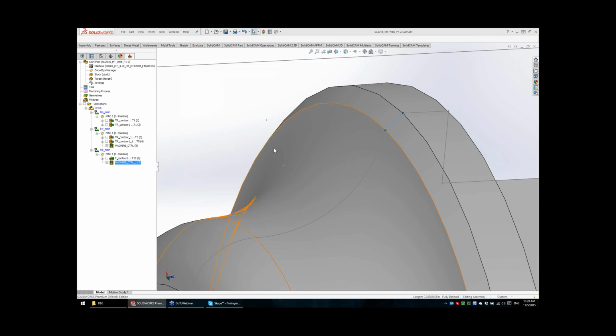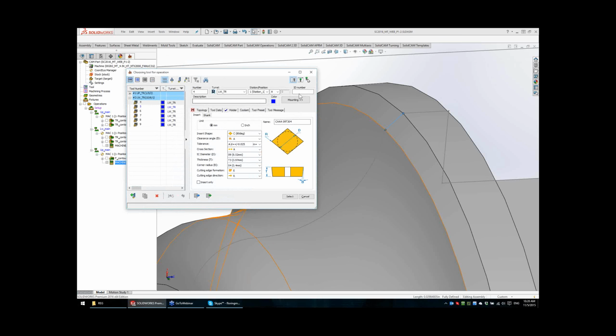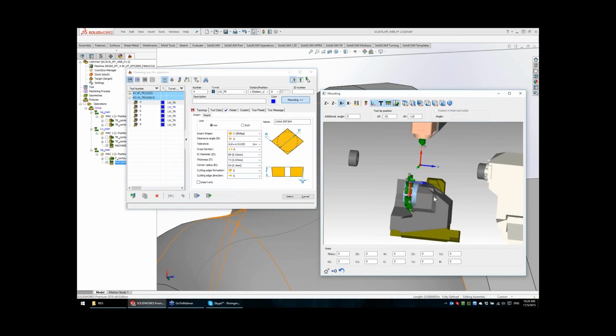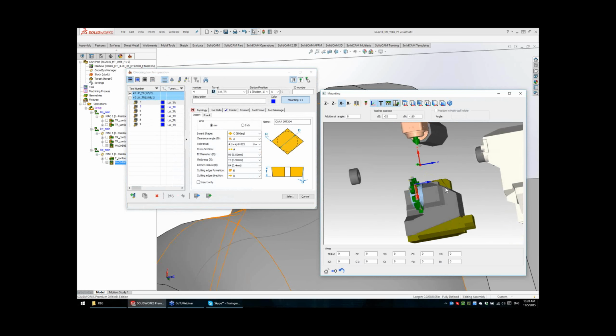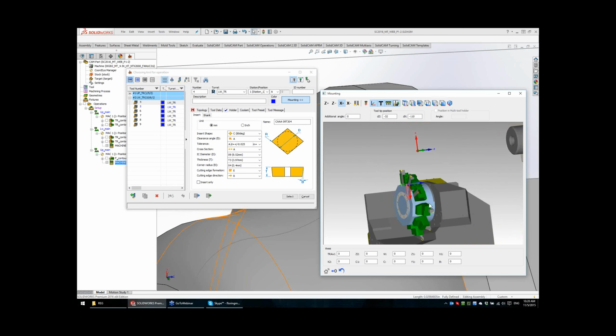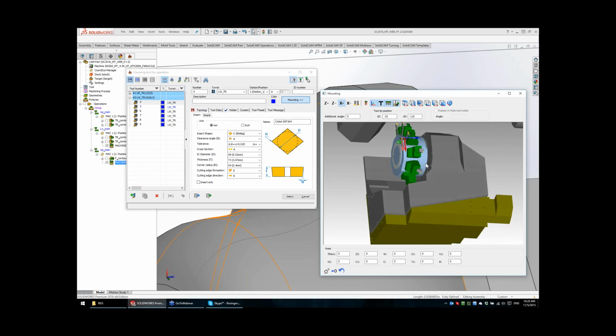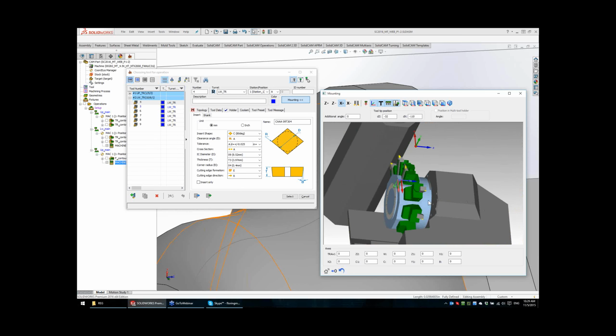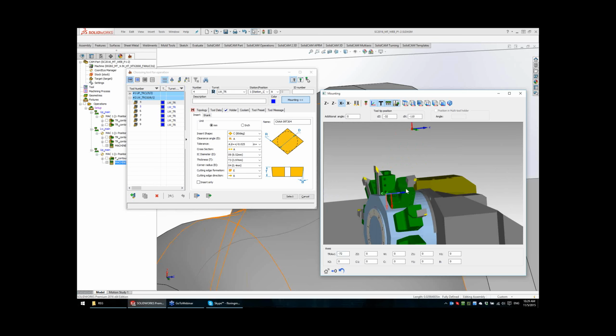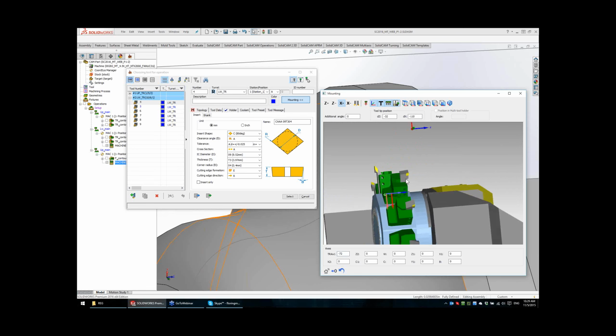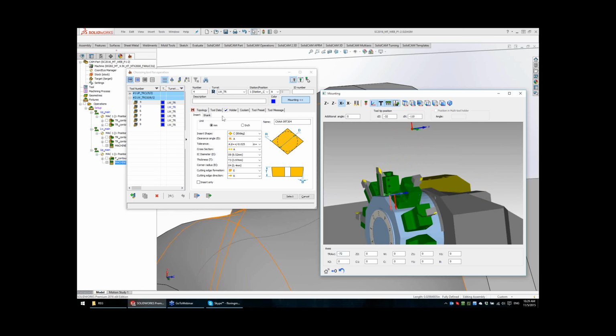And the tool, now we'll select the tool to work on the back spindle. Which tool should I select? I want an 80 degrees insert, which is here. Let's rotate a little bit. Start. Okay. This tool, working on the back spindle, is an 80 degrees roughing tool on station 4. Okay, so tool number 7 is on station 4. I bring it up. That's my tool.